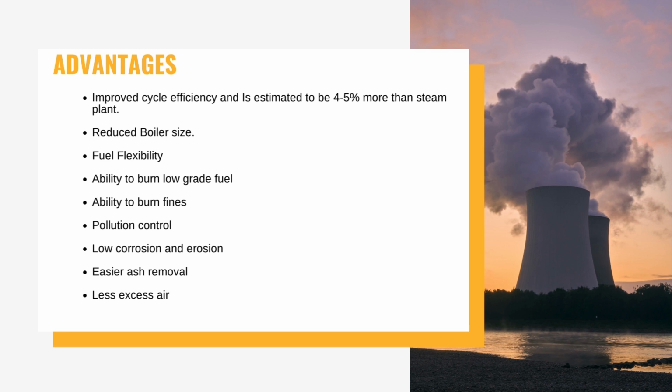High heat transfer rate over a small heat transfer area immersed in the bed results in overall size reduction of the boiler. Fuel flexibility. FBC boilers can be operated efficiently with a variety of fuels. Even fuels like flotation slimes, washer rejects, and agro waste can be burnt efficiently. These can be fed either independently or in combination with coal into the same furnace.